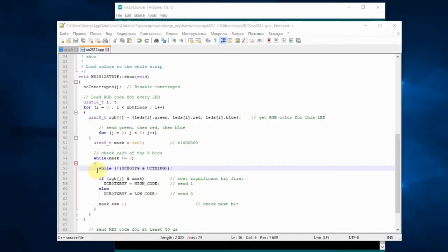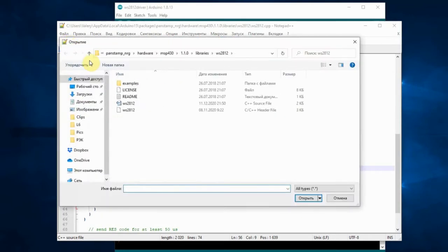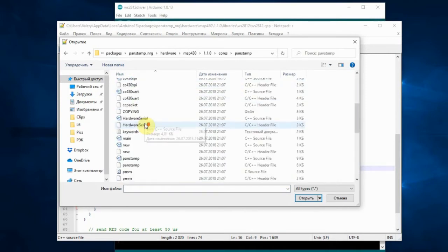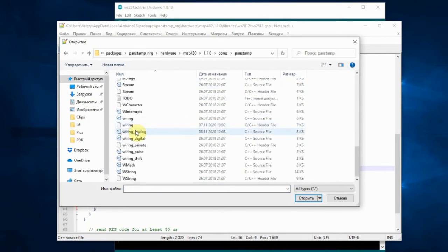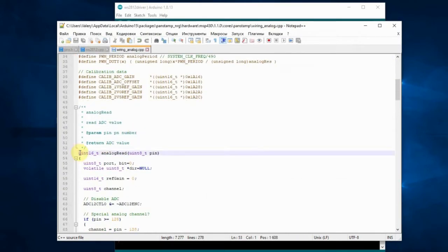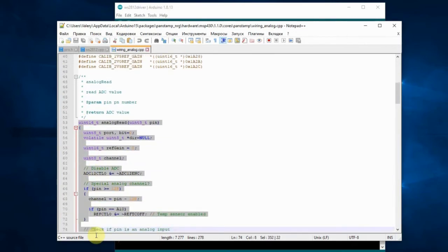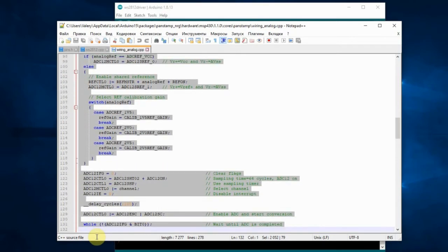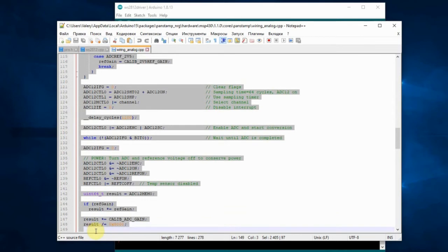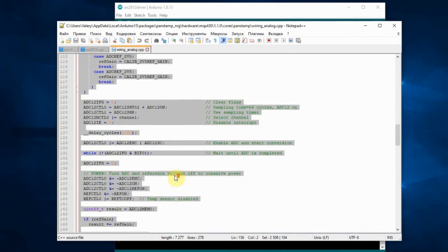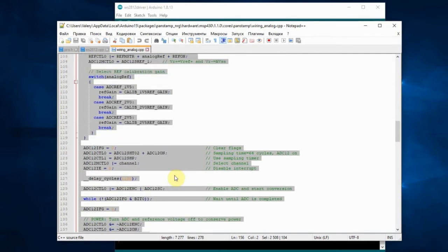Let's move on to programming the analog part. We have to disappoint you a little: the panStamp package does not involve the use of an external reference voltage and parallel multiple high-speed ADC measurement. This is hidden in the body of the analogRead function. Each time this function is started, the analog input is configured, the ADC registers are configured as well, the MCU waits for the system clock to finish 1100 cycles, the value is read after the measurement, and then the ADC is disabled. Can you imagine what delays occur with 100 measurements?